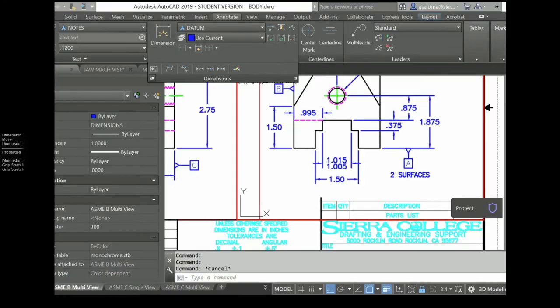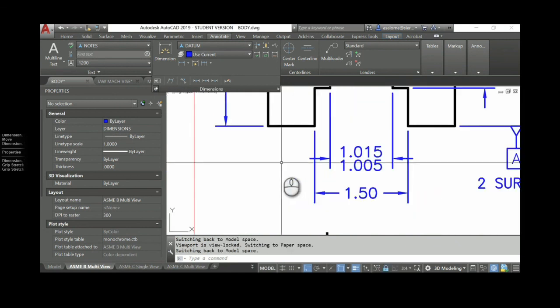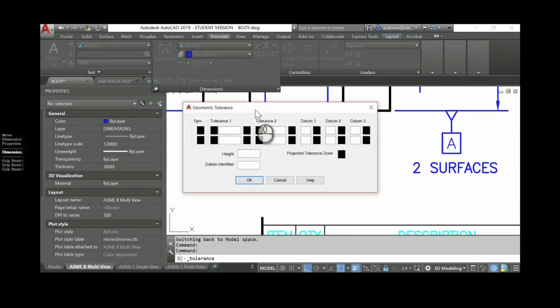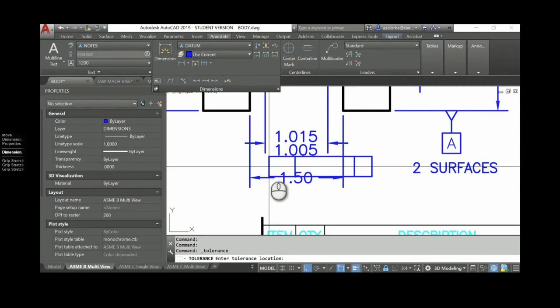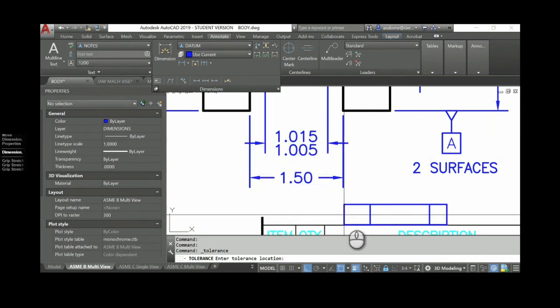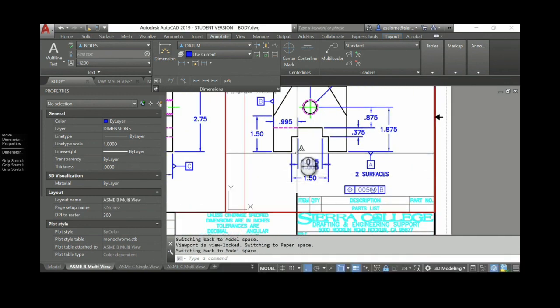All right. So now I need a second line here. The problem is it's not going to fit. So if I go build it, position, there's no diameter here because this is not a diameter. 0.005 at maximum to datum B. Okay, so this needs to be associated with that call out, and it doesn't fit. So I'm going to put it aside. And what we're going to need to do is redistribute how we've dimensioned this.